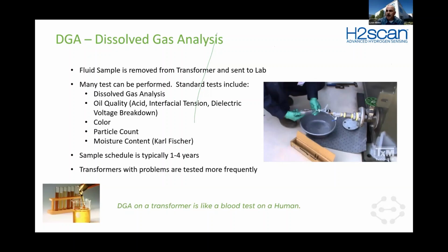We found that outside of substations, people aren't monitoring their transformers at all, aren't taking online oil samples or any of that. So when we talk about taking oil samples, we're typically talking about distribution and transmission substation transformers.